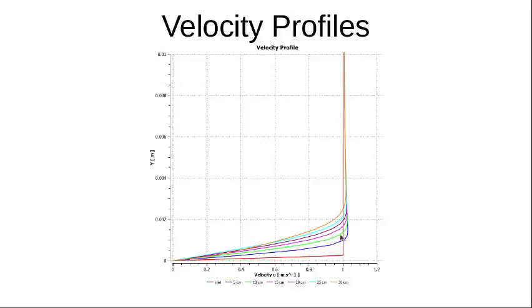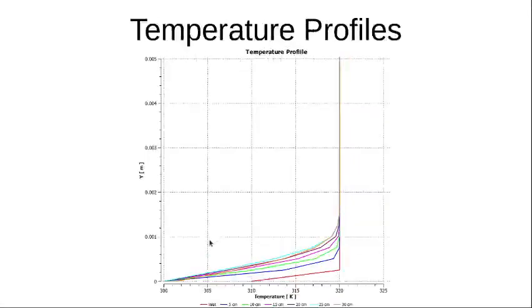Okay, so you can see that the velocity boundary layer is within something like, this is 4 millimeters. The thickness of the velocity boundary layer stays under 3.5 millimeters in the whole region, and similarly the thermal boundary layer also stays under 1.6, 1.8 millimeters in the whole region. Okay, so that is the result that I wanted to show you. Okay, we'll stop.